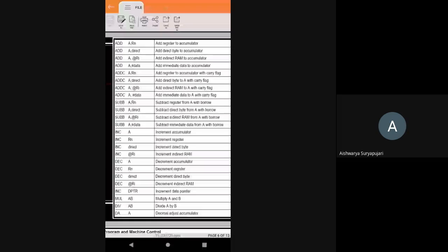From lower 4 bit, that is the 4th bit, carry is being generated and that will go to the 5th column. So that time this carry flag is required. That is the ADDC instruction is required. Otherwise normally for the regular addition ADD instruction is used.